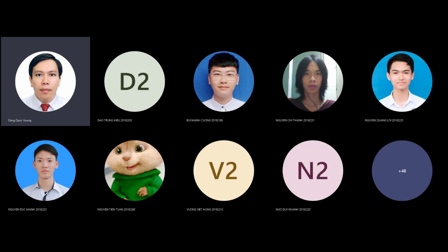Here the cosine of 0.7 corresponds to the inductive load. When the transformer is connected to the inductive load, the voltage drop is bigger than in the resistive case. In addition, when the transformer is connected to the capacitive load, the output voltage of the transformer is very high in comparison with the rated voltage.